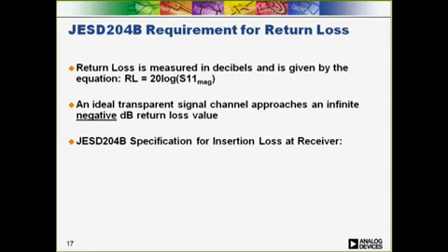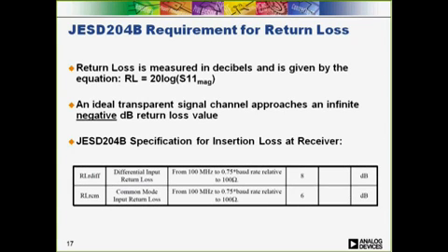Return loss is also measured in decibels and given by this equation here. Again, since the log of a value that is less than 1 is a negative value, return loss will always have a negative value. In fact, in the ideal case where the reflected power is 0, return loss would be -infinity. The JESD204B specification provides the maximum return loss specification for differential and common mode inputs given in the chart here. Don't be confused by the positive values here. Since they are defining losses for return loss and common mode return loss, the negative value is implied.